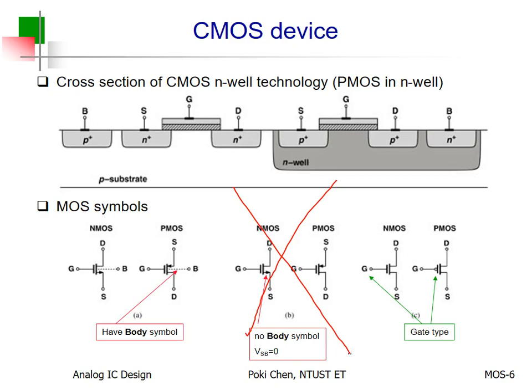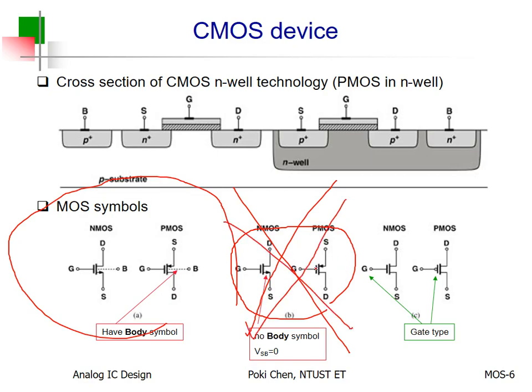Wow, that is simple. Let's apply it. Because from the technology file from TSMC or UMC, they provide not only the complete version, but also the simplified version. For whom? Not you. For digital IC designers, not you. But ridiculously enough, almost all those digital designers pay no attention to this. Only us. We pay much attention, but this is quite misleading. Again, unless you can short your source and body, which means no body effect, unless you can promise me that, otherwise, don't touch.